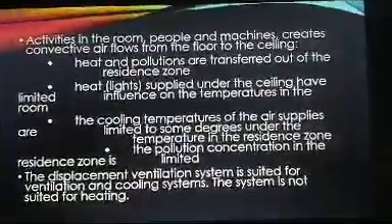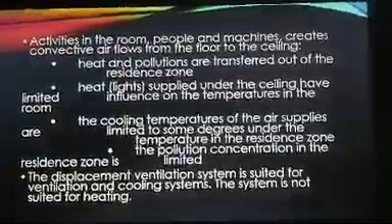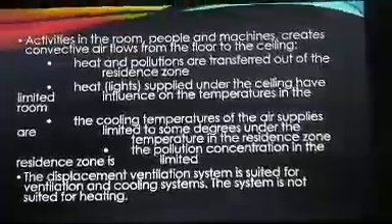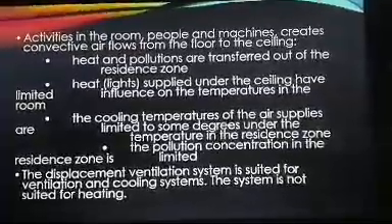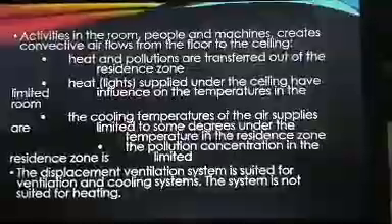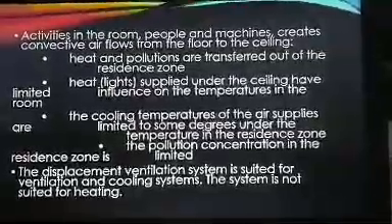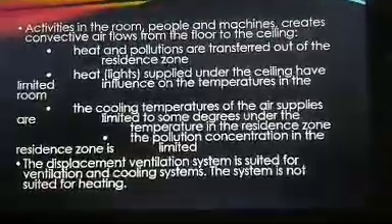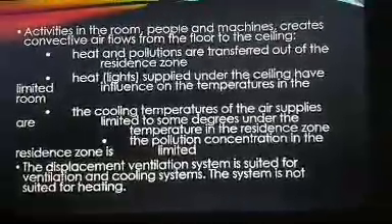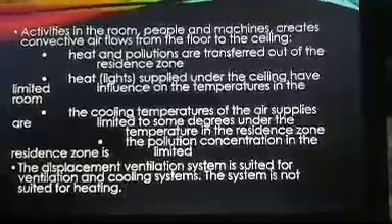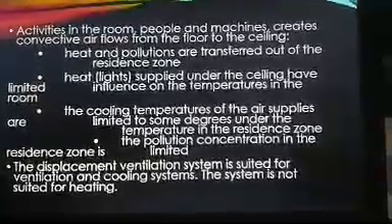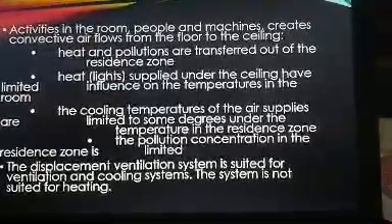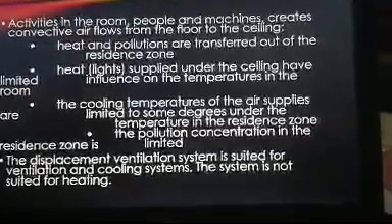Activities in the room, people and machine create convection airflow from the floor to the ceiling. Heat and pollution are transferred out of the residence zone. Heat like supply under the ceiling have limited influence of the temperature in the room. The cooling temperature of the air supply limited to some degrees under the temperature in the residence zone. The pollution concentration in the residence zone is limited.